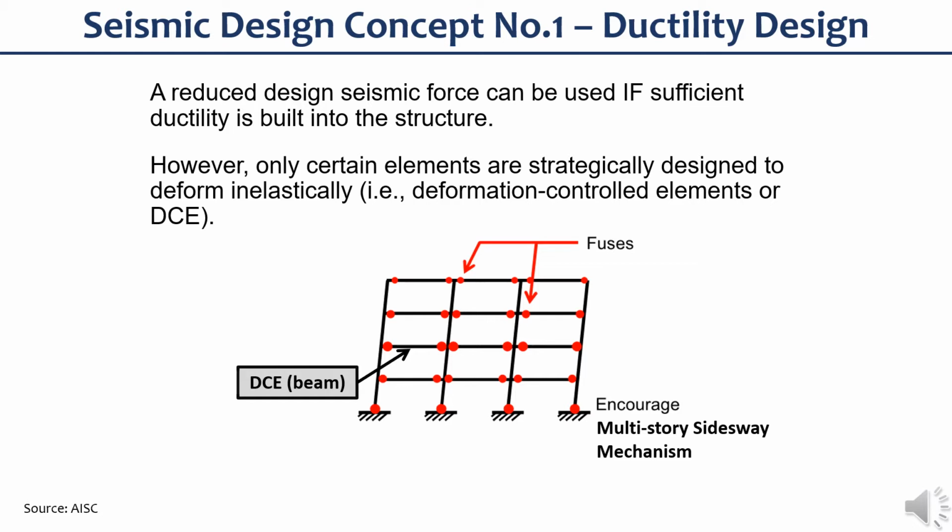The first seismic design concept is what we call the ductility design. A reduced design seismic force can only be used if sufficient ductility is built into the structure. However, only certain elements are strategically designed to deform inelastically. That is, the deformation controlled elements, or DCE. Note that in SMF, the DCEs are the beams.